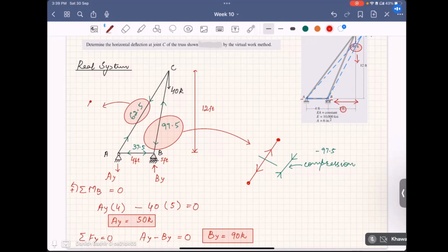So this is a joint attached to the joints. Okay, so it is having a force like this attached with the joints. So I am telling that 62.5 is a tensile force. I will show you how it's a tensile force. If I draw a section like here, and if I take a member there, what will be the internal forces to balance this? So to balance this arrow, the force should be acting like this. So actually it is elongating the member.